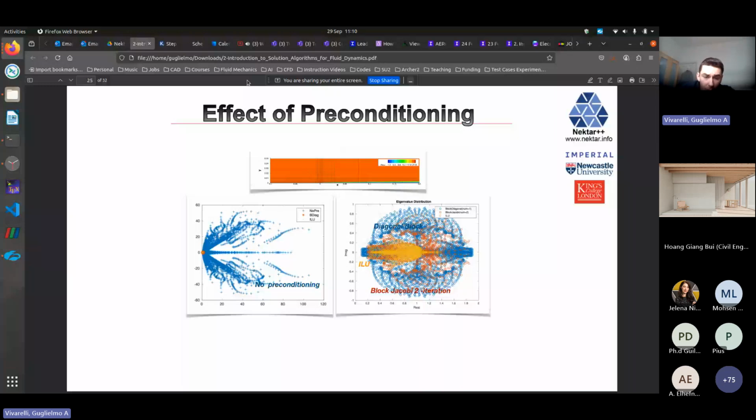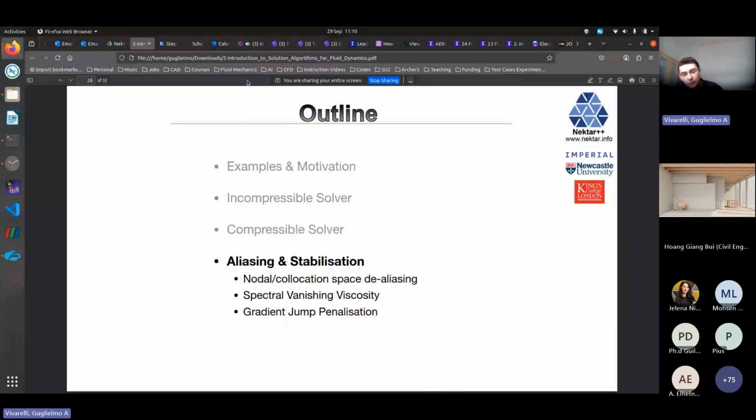Okay, so I've highlighted the compressible flow solve, and we move on to discontinuous Galerkin. We require the transfer of information from one side to the other of both the convective terms, which you do through upwinding, and the diffusive terms, which you do through some mix and match or some averaging, because it doesn't really have a direction.